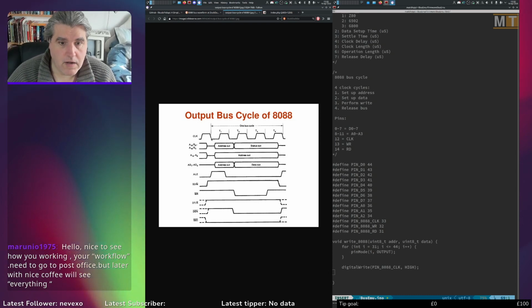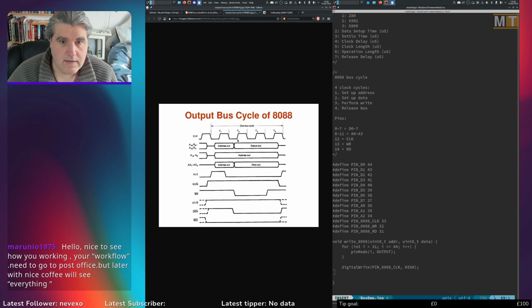So we drop the clock, set the address, raise the clock. Drop the clock, set the data, raise the clock. Drop the clock, raise the clock. Drop the clock, raise the clock, release. Done.